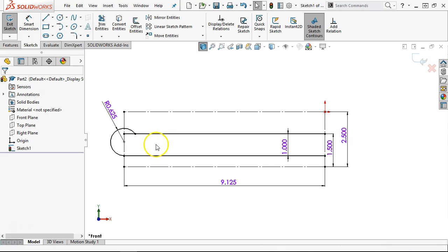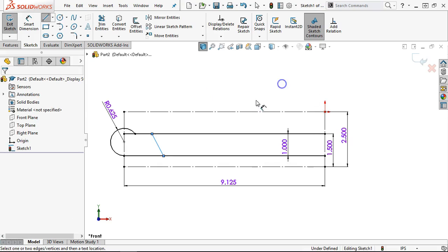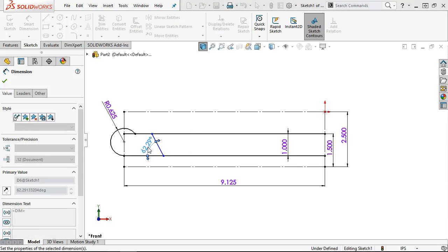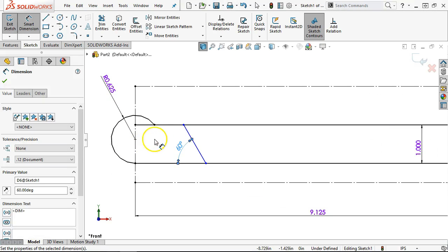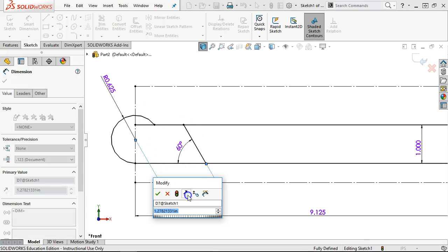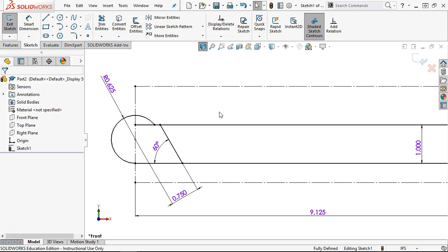Let's see, there is a back relief. It almost looked like it was in blue. No. Okay, so there's a back relief, and that's another interesting way of dimensioning, but let's get it in there. So 60 degrees off the horizontal, and then from the center of the arc back, 0.75. The functional gauging on that one's got to be a little weird, but I guess it's just a relief and 2 decimal places, so that one's pretty wide open.